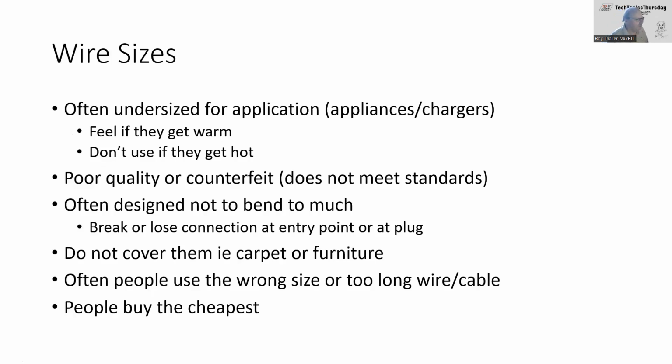Wire sizes. Typically, if you buy appliances, the wire can be undersized. So feel it to see if it gets warm. If it gets really hot, don't use it. You probably put on the wrong size.